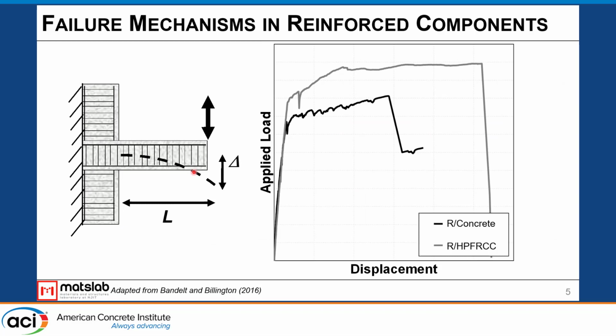One unique aspect from a seismic design perspective is how differently these members behave when you load them from initial loading to failure. This is a representative load displacement plot. Generally speaking, a UHPC type system will have a higher first cracking load. From a structural perspective, like reinforced concrete, the steel eventually yields. The main difference is how they fail.